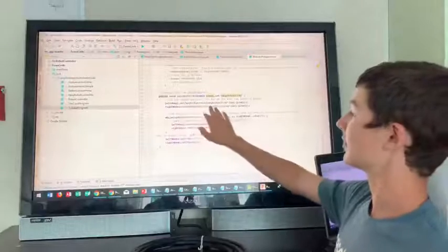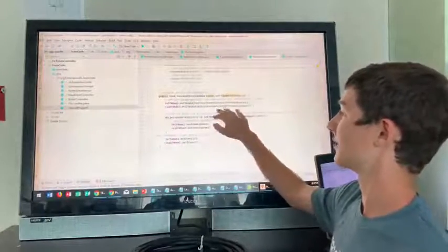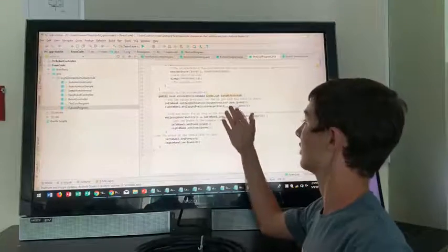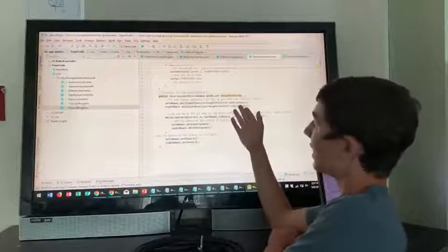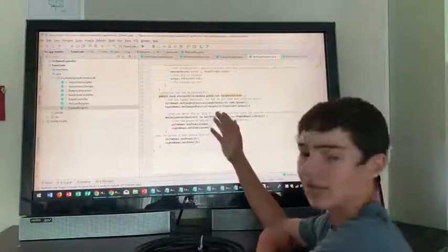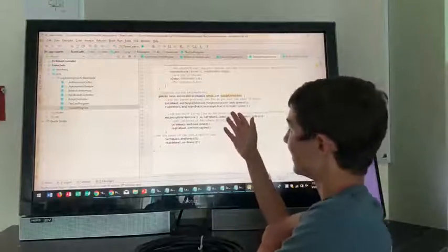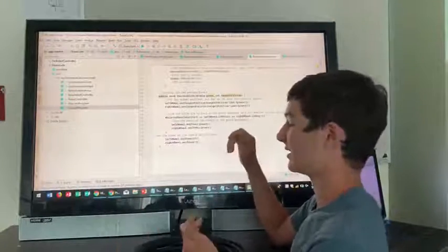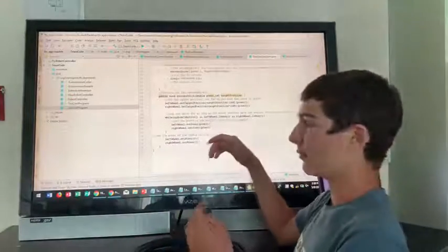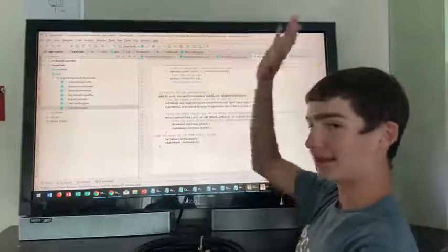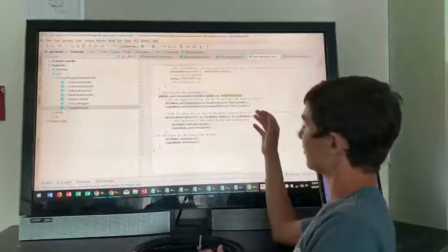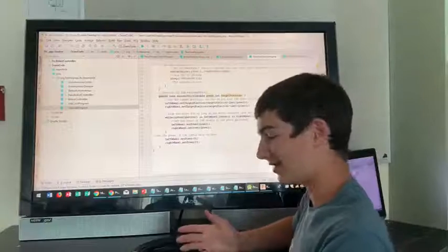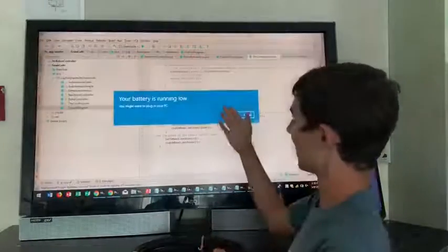So we're going to set our target position by taking our input target position, which is an int, and here I have it set to 2000. And we're going to make sure that the int of power matches, because target position is either going to be negative distance or positive distance. And we don't want the target position to be positive and be going backwards. For instance, if we're starting at 0 and we're going to the position 2000, then we don't want to have our power going negative, because we are never going to reach our destination. So that would not be a good thing to happen.